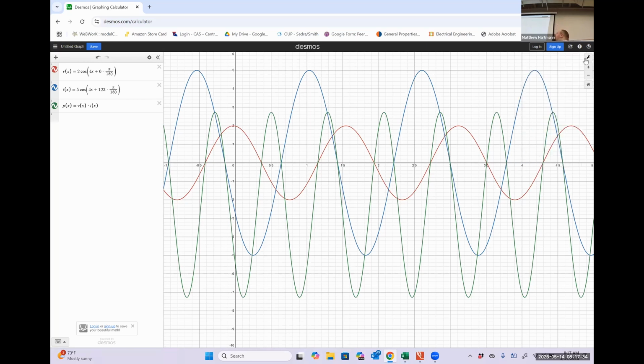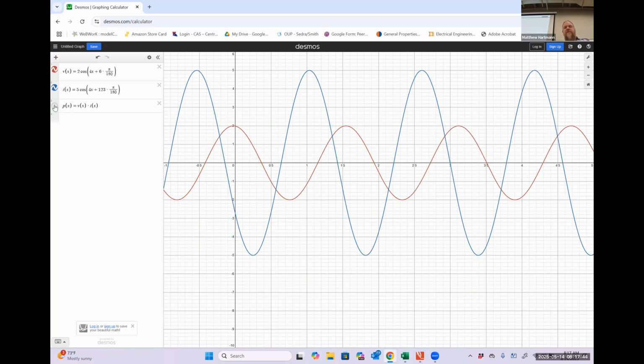Okay, so I know that this graph is really busy right now because we have 3 signals on it, but I want to point out a couple of things. So I'm going to turn off this power curve right here. The first of which, and this should be intuitively obvious, our voltage signal is just a simple sinusoid, meaning that it is oscillating between its maximum value of 2 and its minimum value of -2 over and over again at an angular frequency of 4 radians per second, because that's what I decided omega was going to be for this example.